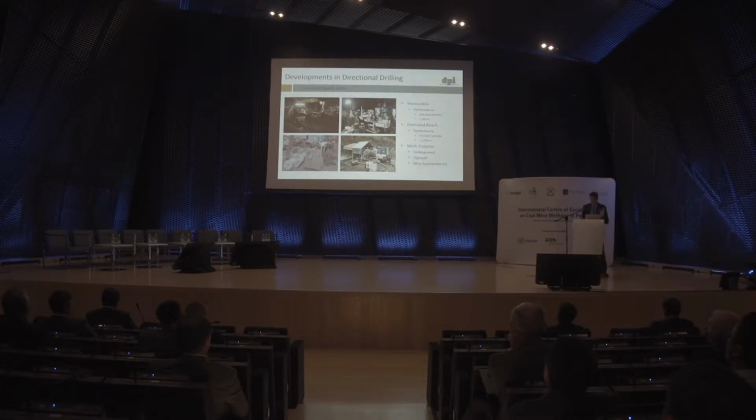So what we've done ourselves is built drills, or have had directional drills built, with thrust capacities of twice what's commonly used. So typically, I would say since the early 1980s, we've been using drills with 200 kilonewtons of push force, and now we're using drills of over 500 kilonewtons.